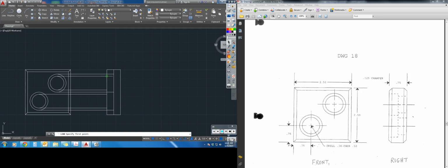And notice if I hover over the endpoint and then I go straight out to the right, it creates a little X that allows me to be positioned at the same location. Or what you can do is start at that endpoint and draw straight across, and then I can trim off this extra point that I don't need. Okay, I think it's probably easier to just start at the endpoint and go straight across and then trim. So I'm going to do that. Okay, so let's trim it now. I'm going to cut away this and this.